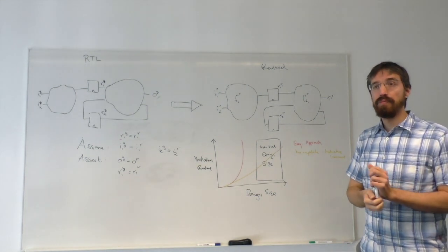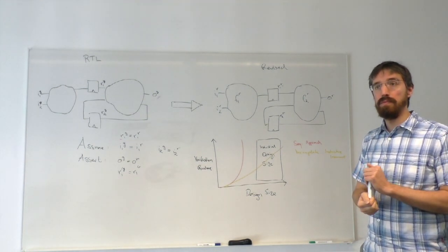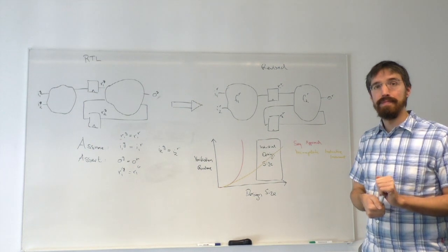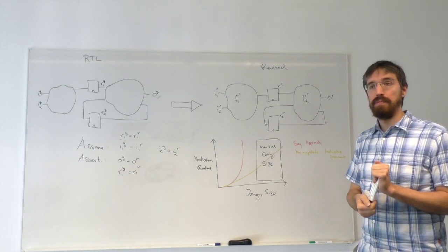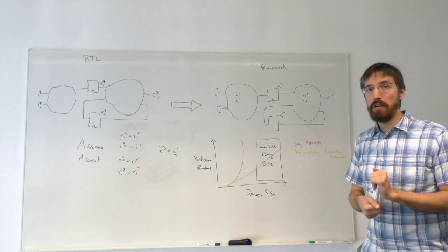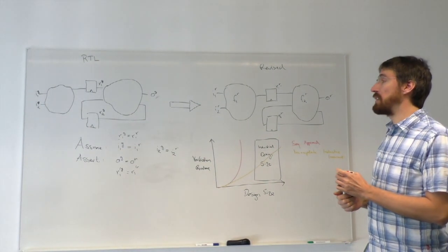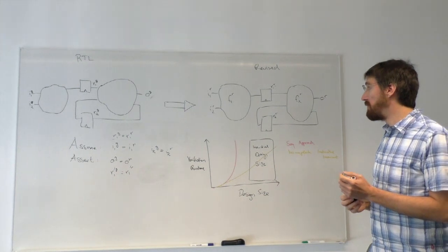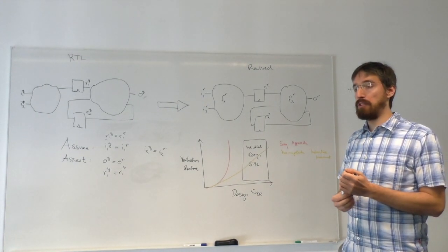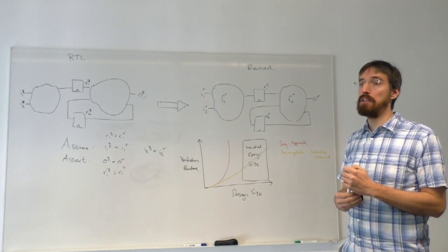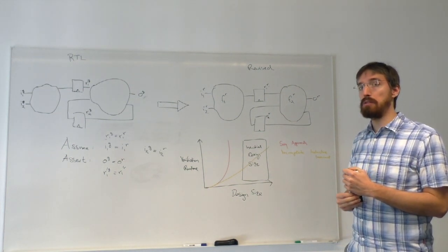One of the reasons that people use FPGAs is they are programmable. They're often making last minute changes. If you do make changes, do you have to go through this process again? The verification you definitely need to do again. The inductive invariant, in case you needed to do manual transformations to it, may be the same, but it depends on what the synthesis tool was doing.